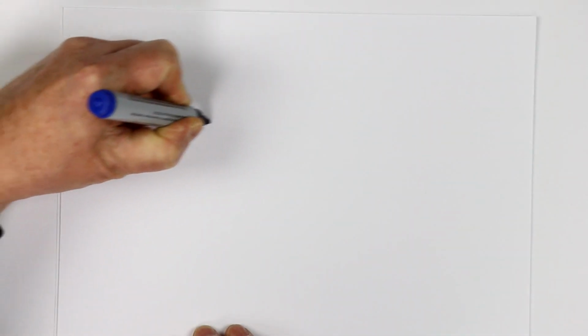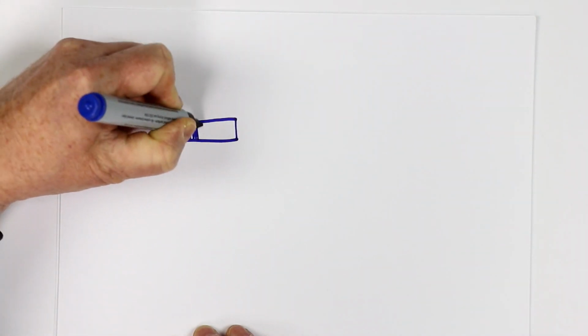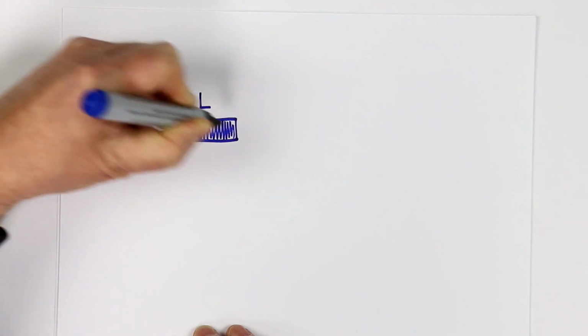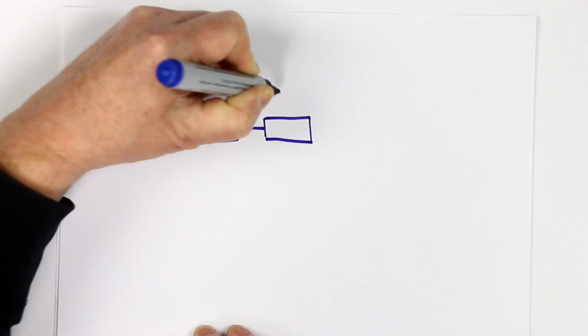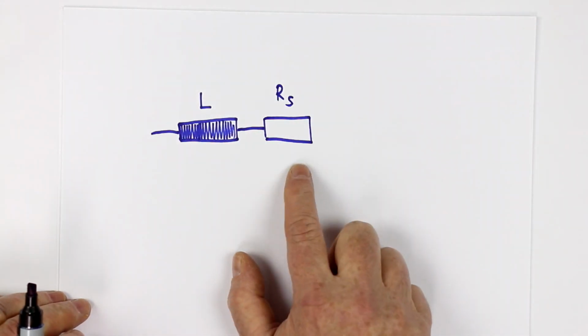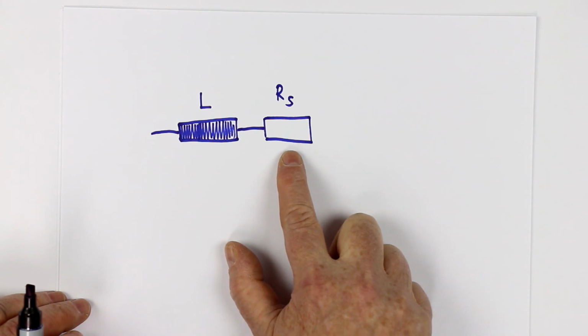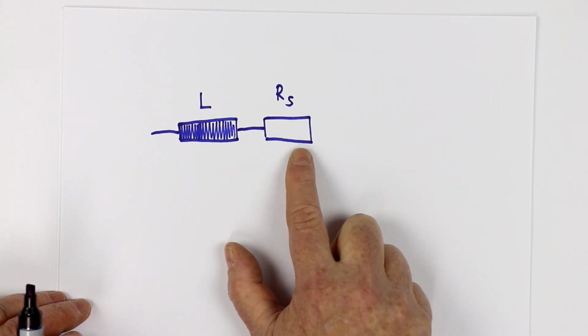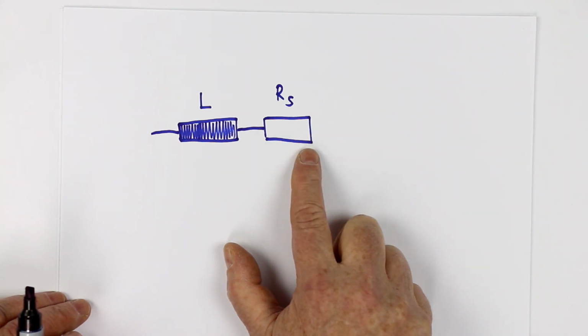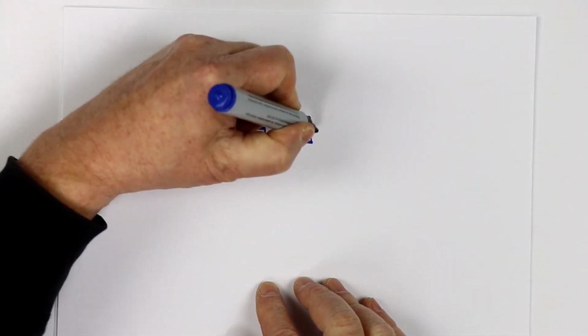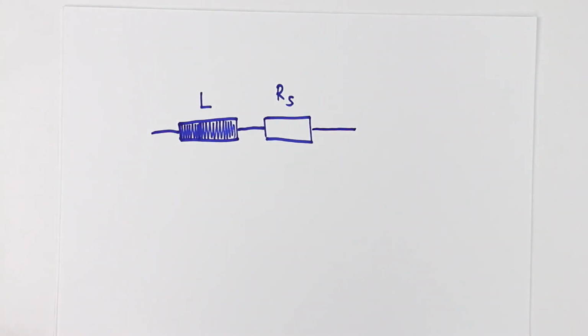A real inductor does not only consist of the inductor itself, but you have at least the copper resistance in series. But the copper resistance comes into play only for DC currents. When the frequency increases, there are additional losses. They come from things like the skin effect, the proximity effect, and losses in the ferrite material on which most inductors are wound.